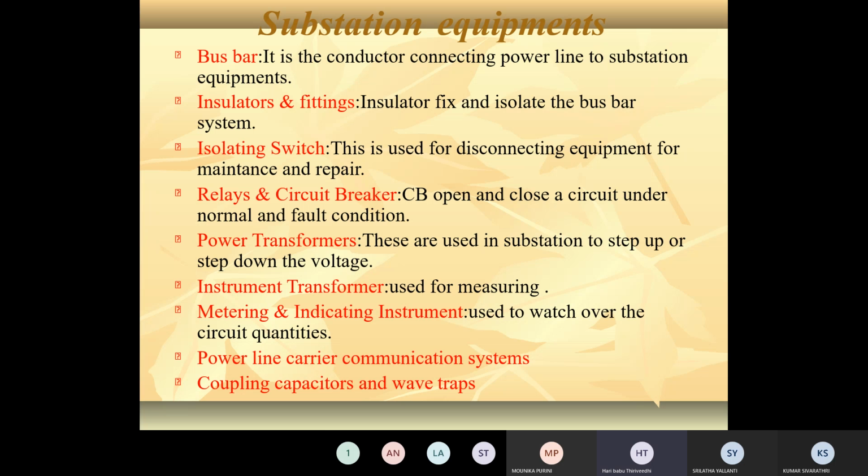So totally, the transmission lines and distribution lines in a substation may operate at high voltages and high currents, that is thousands of amperes. But for measuring these thousands of amperes, ammeters and voltmeters are not possible and shunts are also not possible. That's why the instrument transformers, that is current transformers and potential transformers, are used.